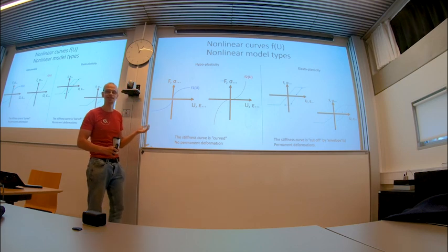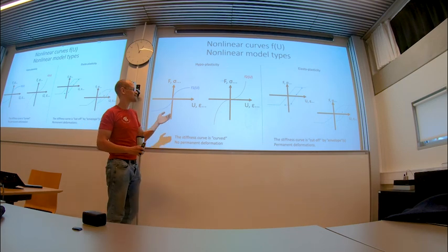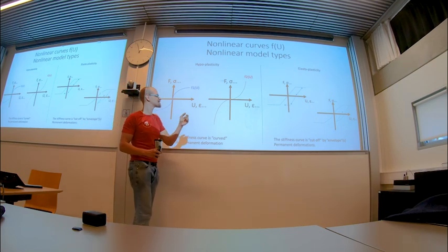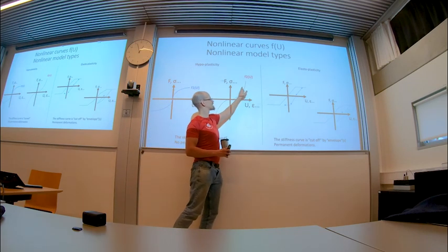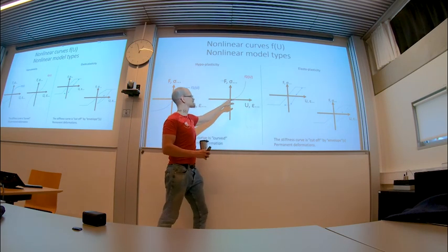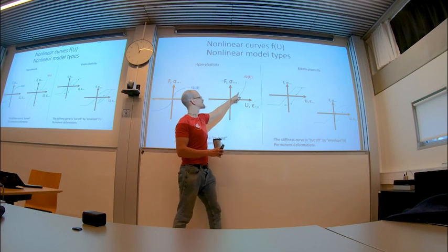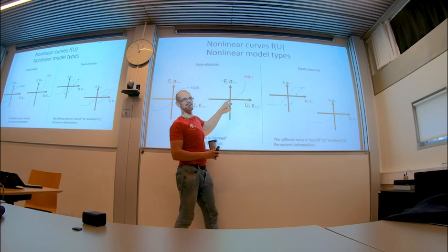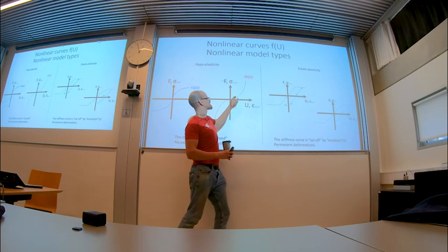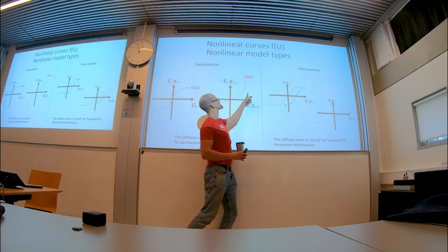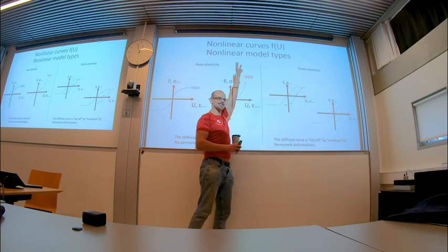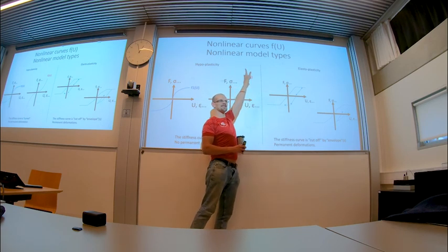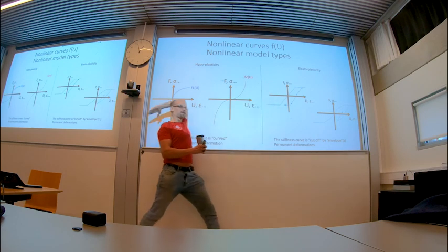Computer games still use this theory, like collision detection boxes. And maybe you want something that's very rigid, maybe you don't. This can cause instability, because if you guess a displacement up here, all of a sudden the reaction force is infinite. And then how do you compensate for an infinite reaction force error? You compensate by adding an infinite displacement backwards, and it explodes.